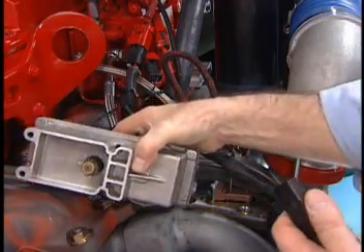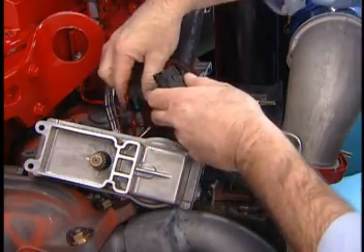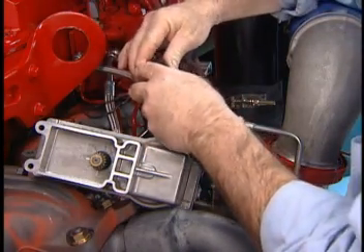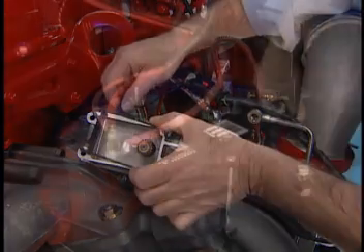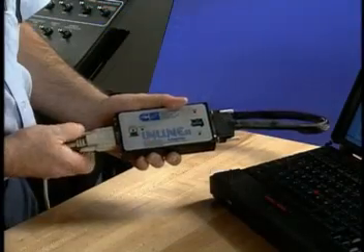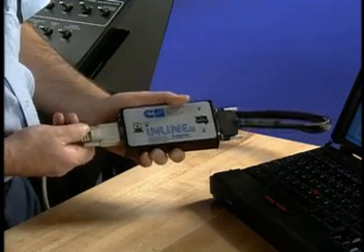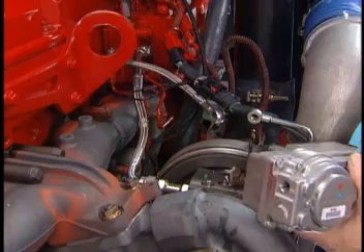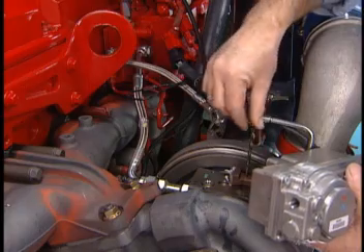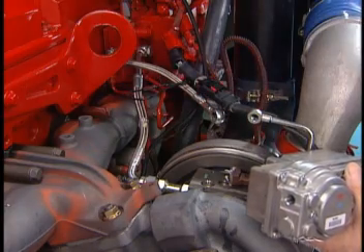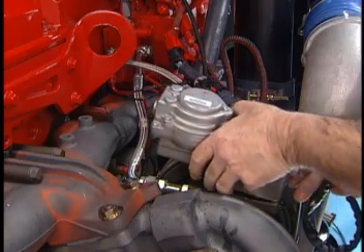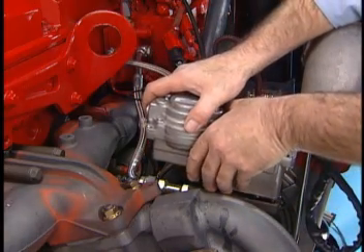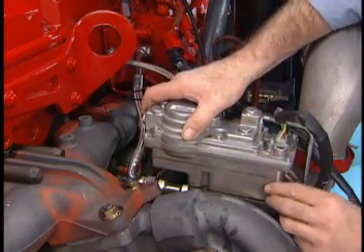Connect the actuator to the engine harness. Install the new gasket. Connect the batteries. Connect Insight using a designated inline connection. Align the actuator and gasket assembly with the turbocharger bearing housing face with the two lower cap screws. Align the actuator to the bearing housing and slide the actuator into place.